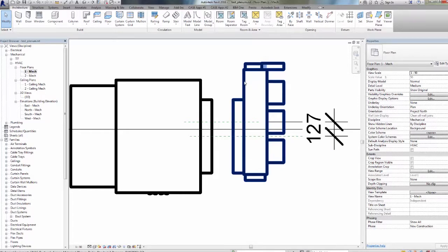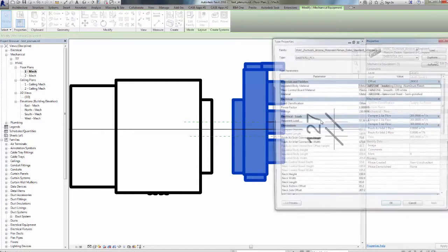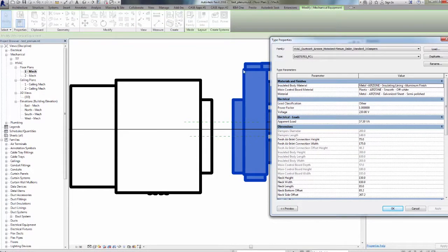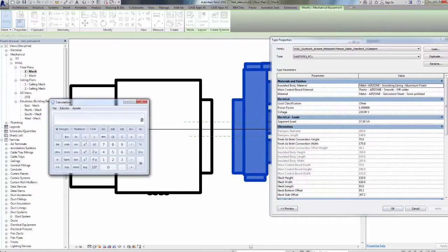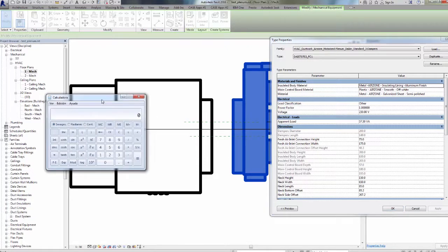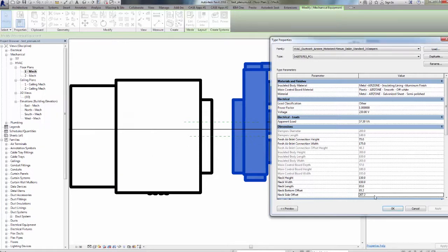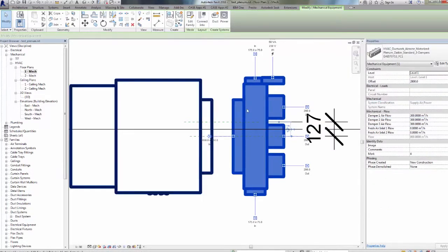In order to center the plenum, it would have to be displaced the distance resulting from the difference between the center of the unit and the center of the plenum. Then, to this gap we have to add 127.2. If the gap is 267.2, when deducting 127.2, it results 140, which could be the side gap to introduce in order to center the plenum with the reference to the unit.